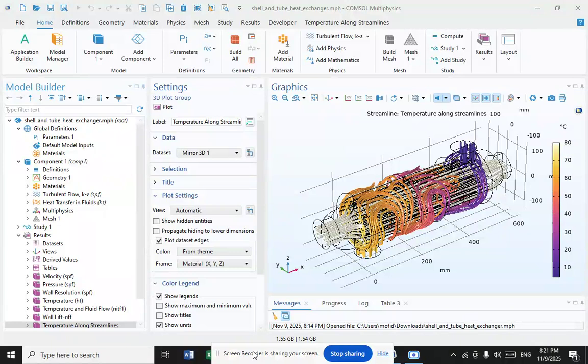For efficiency, heat exchangers are designed to maximize the surface area of the wall between the two fluids while minimizing resistance to fluid flow through the exchanger. The exchanger's performance can also be affected by the addition of fins or corrugations in one or both directions, which increase surface area and may channel fluid flow or induce turbulence.